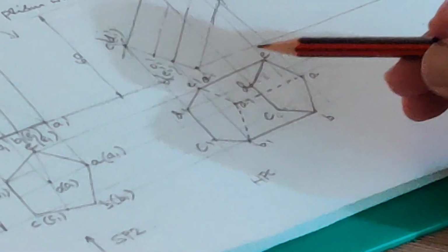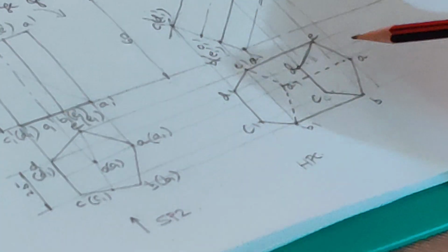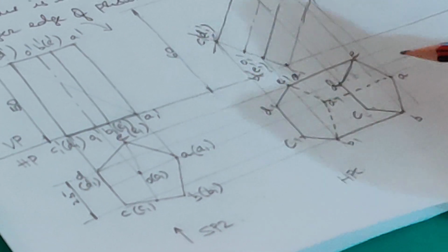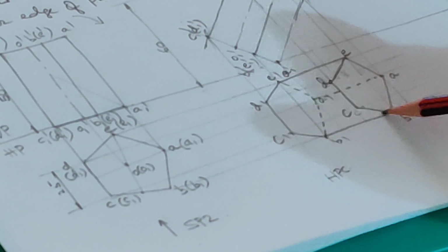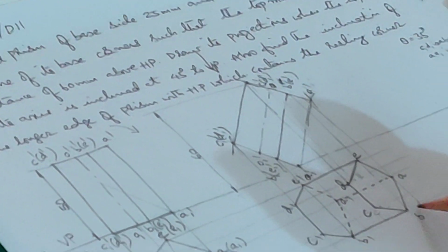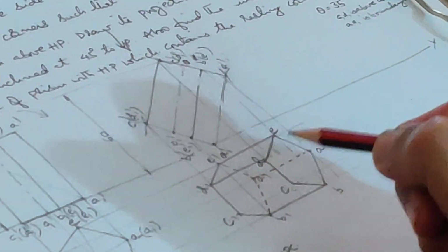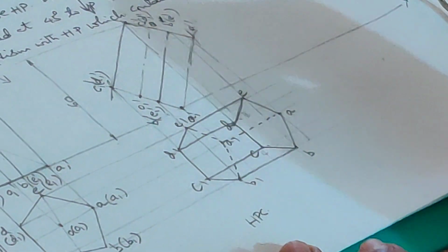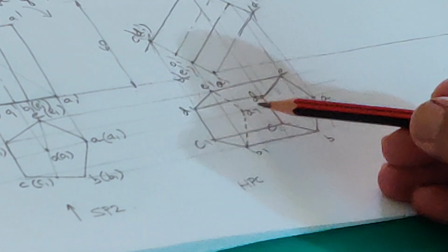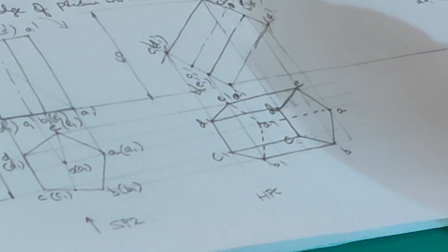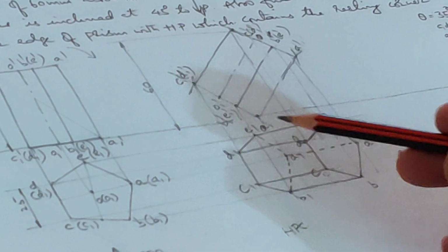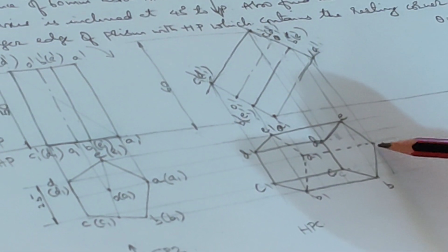As I was mentioning earlier, for the inner lines, the connections depends on what they are. If the inner lines are dotted, the connection also is dotted. If the inner lines are solids, the connections also are solid. So here the inner lines are solid. These are the connections. They become solid. Means invisible. You will not have a case where the inner lines are dotted and their connections are solid. That will not be the case any time. Okay? If the inner lines are solid, their connections are also solid. If they are dotted, their connections are also dotted.